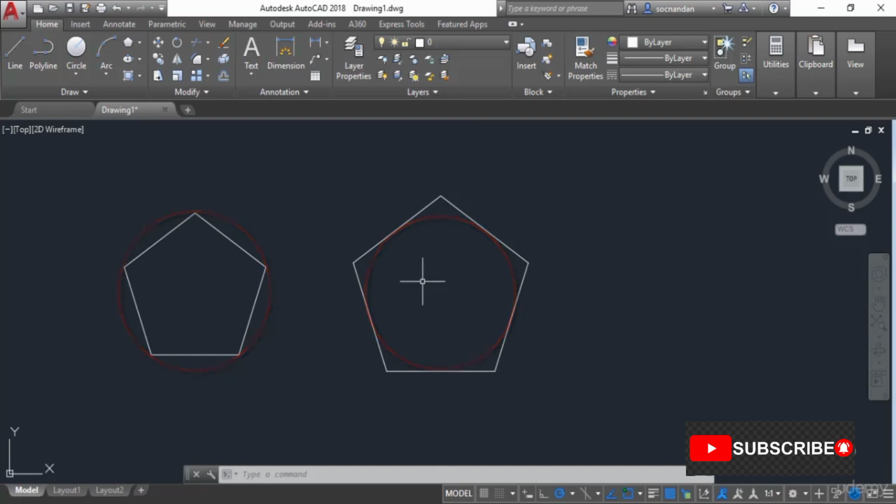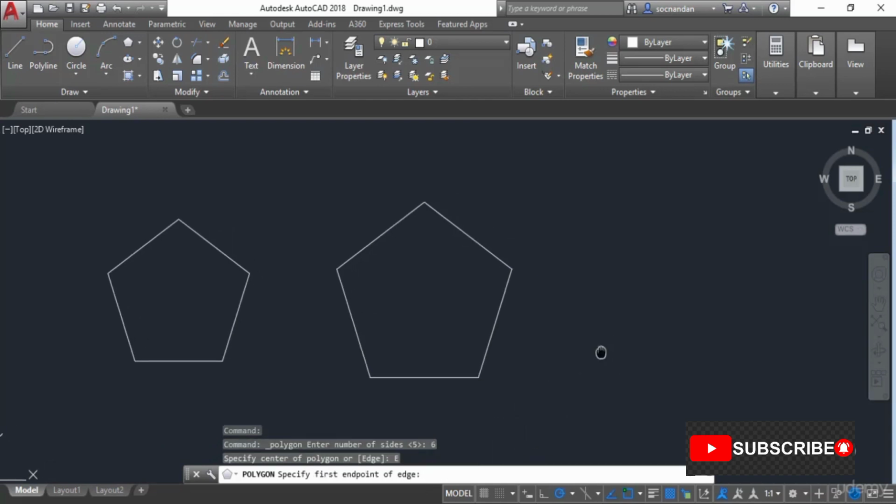So we have one more method of making the polygon, and using that method you can make a polygon with a known value of its side length. So let's say that we know the length of the side of this polygon, and we want to make a cyclic polygon in such a way that all the sides of that polygon are of the length which we specify. So for that you can select the polygon tool, and once again enter number of sides, and let's say that in this case we want to enter 6 as number of sides and press enter. Now you can specify the center of polygon to make either an inscribed or circumscribed polygon, or you can simply click on this edge option, and using this edge option you can make the desired polygon.